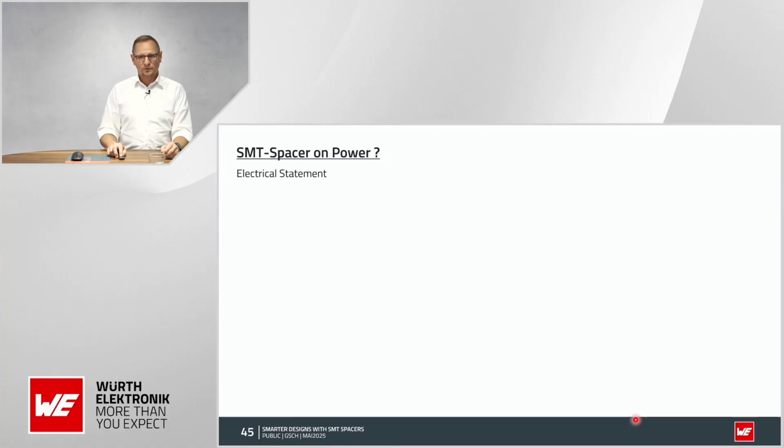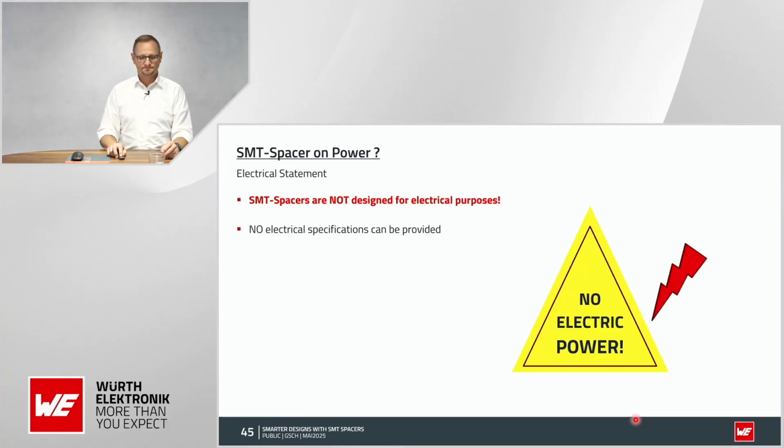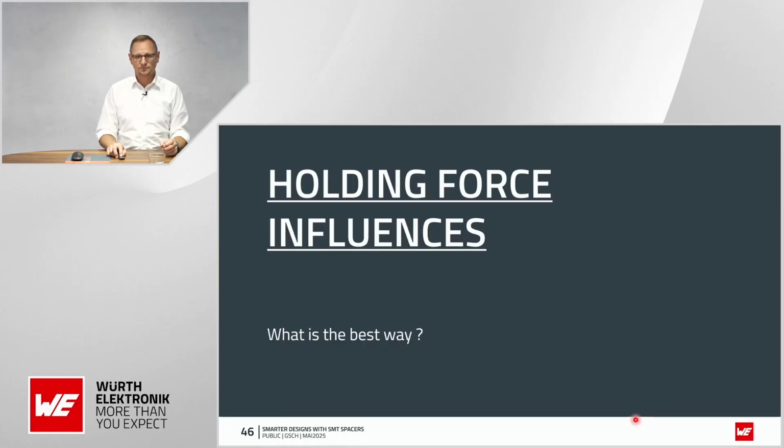SMT spacer and power? No. These SMT spacers are not designed for electrical purposes, as you can read here. Of course, they are made of steel, but steel is not a good conductor, and therefore we also have our high power terminals. If you want to lead the current over it, this is just not specified. Everything else is up to you.